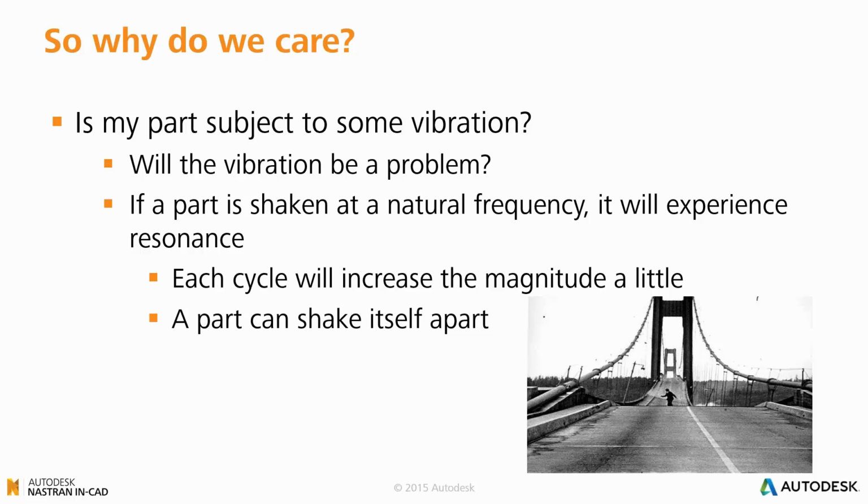So the key takeaway here is that no matter whether we're talking about bridges, maybe you're a fan manufacturer looking at the rotating mass of an object that's running at a specific RPM, or maybe you design telescopes and you're concerned about the optical precision of your devices, components will resonate at their natural frequency. It's in our best interests to take this in mind and try to avoid operating our devices in those areas, or look at potentially shifting the natural frequencies of our designs to avoid these unavoidable loads that we could be imparting on the design.